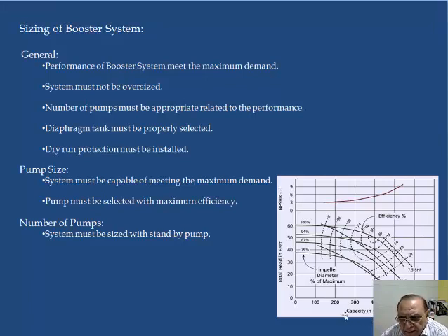And this is represented by the flow in GPM and the head in feet. So for the selection of the pump, we must select our pump's requirement to fall in this range, which gives the maximum efficiency.